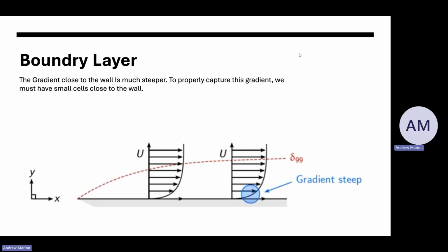If you're dealing with boundary layers, sometimes you might not be, it is important to calculate the height of the first cell required. That is called a Y plus calculator. We did that for you last time. If you want, on day 3 or so, we can show you how to do that. It's a little complicated, but there are some online tools you can use for it. Essentially, if the cell height near your boundary layer is larger than the size of your boundary layer, it won't calculate that boundary layer because the cell is too big. It needs to be as big or smaller than that.